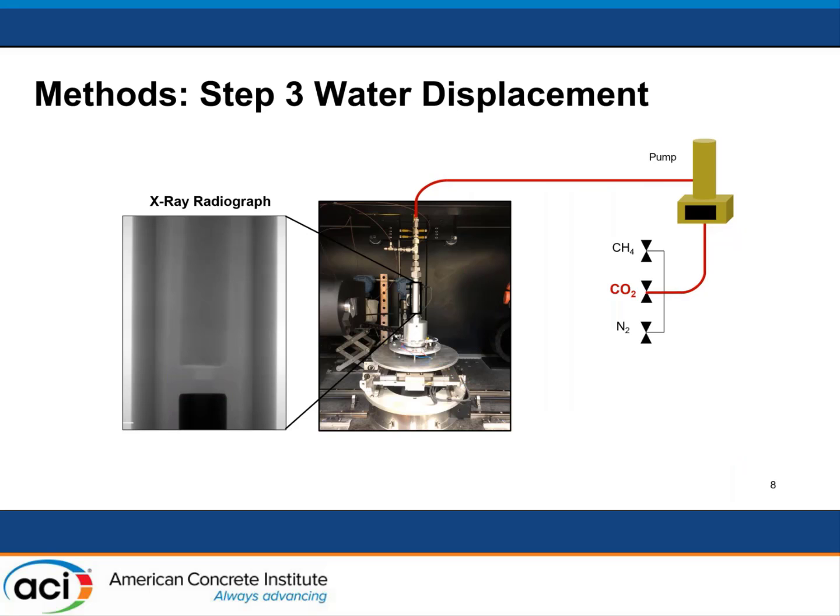And then the next morning, I came in and manually injected water using clear tubing until I could no longer visually observe the injection. And then I used X-ray radiographs and that Teflon spacer I mentioned earlier to actually monitor the water filling just below the sample, because we wanted to make sure that we brought the water in contact with the sample, but didn't inject water into the sample, because that would not be the capillary suction process.